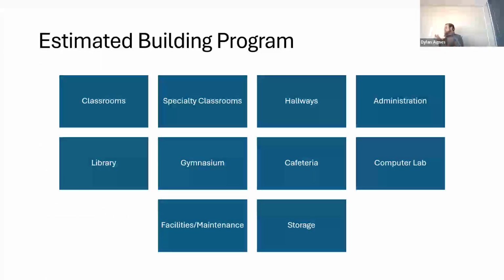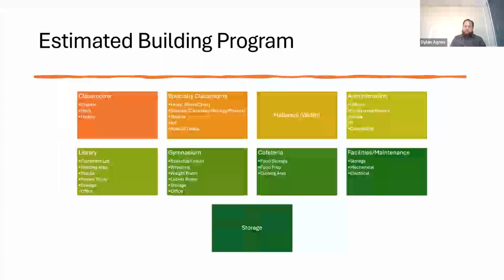But if you don't know your building program, we want to estimate it. Depending on the building type, you should be able to fill out the majority of the building program. So here's my fictitious high school that I'm designing the program for. Now this works for the building area method, because we can estimate the whole building size based off these programs, but not for the space by space method, once you get a little more specific.